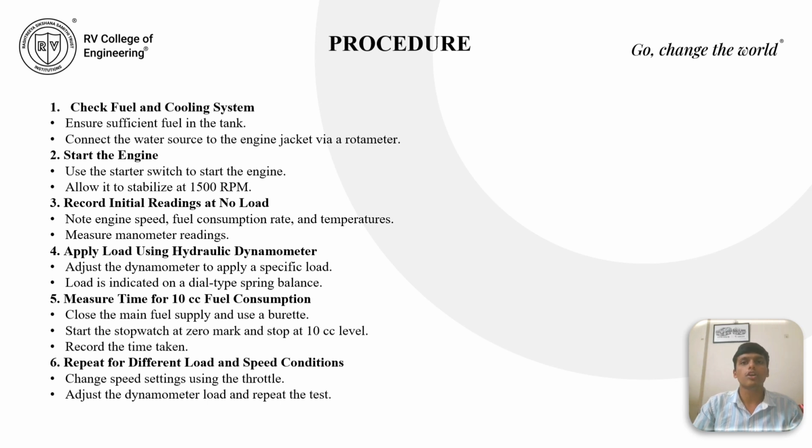Increase the load using the dynamometer and maintain the required speed. And measure the fuel consumption time. Use a burette and stopwatch to record the time in seconds. Similarly, repeat for all the different readings. Perform tests for all combinations of load and speed.